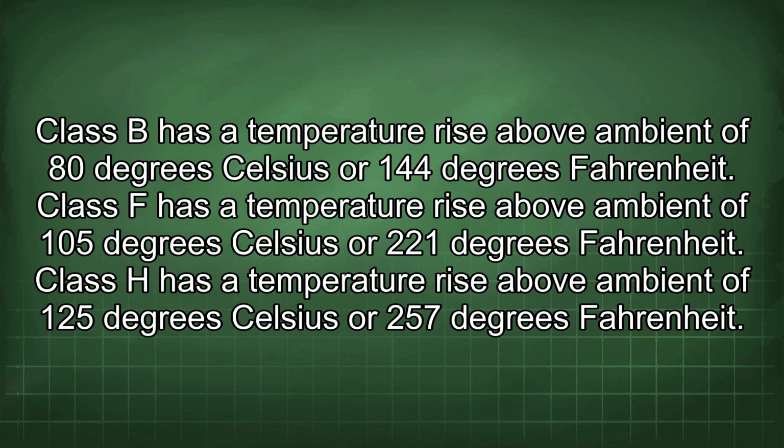Class F has a temperature rise above ambient of 105 degrees Celsius or 221 degrees Fahrenheit. Class H has a temperature rise above ambient of 125 degrees Celsius or 257 degrees Fahrenheit.